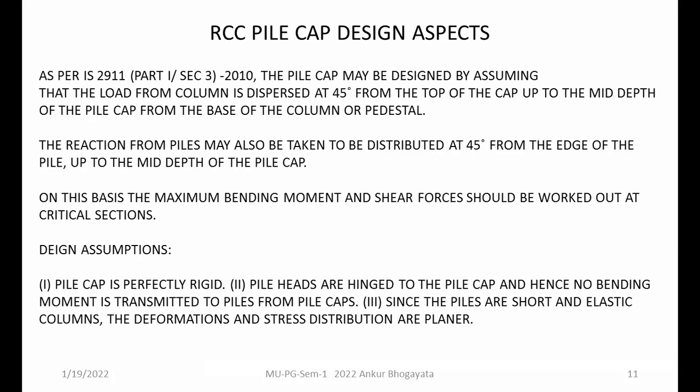However, in actual practice or in reality, there is some effect of rigidity at the pile cap and pile itself, which introduces some sort of negative bending moments at the connections. But these connections are very well taken care of by the amount of steel that you provide in pile caps. You have already seen that the pile caps are provided with a tremendous amount of steel.